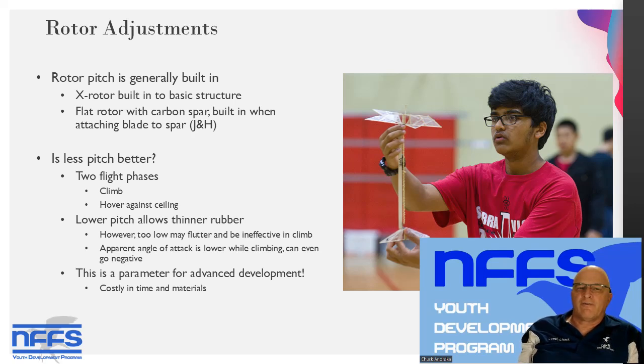There are two phases of the flight. There's the climb, and then it hits the ceiling and it hovers against the ceiling. If you get too low of a pitch on the rotor, then when the helicopter is moving quickly toward the ceiling, you can actually stall your blades. There's a minimum pitch you need. I think it's probably going to be in the 6 to 10 degrees at the tip. And that's for an X rotor.